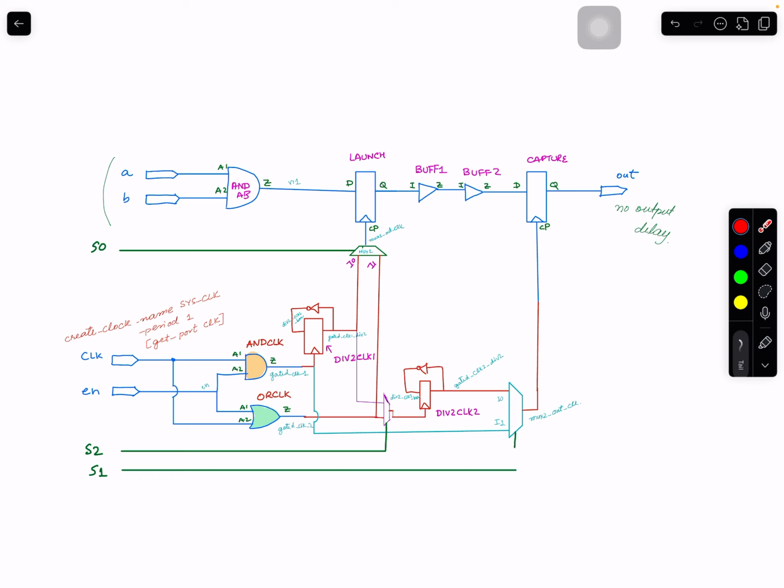Okay, now look at this from the mode's point of view, the same thing. What happens now? You have one clock, you define create_clock here, remember? Then you defined a generated clock here. Then you created a generated clock here, but with this master and another master, because the two different frequencies are coming into this. Okay, a cleaner approach, and I remember I told you, it looks like I'm missing connectivity here.